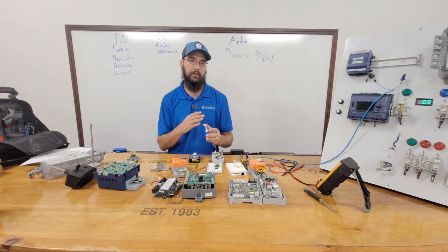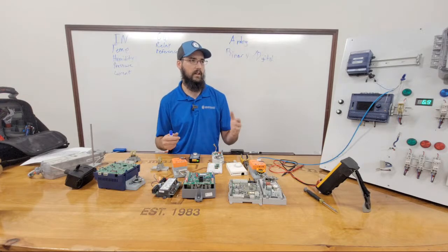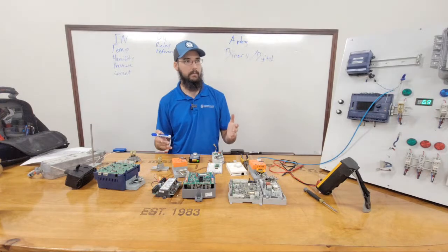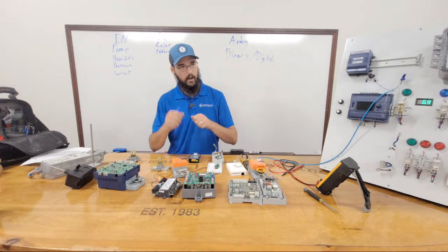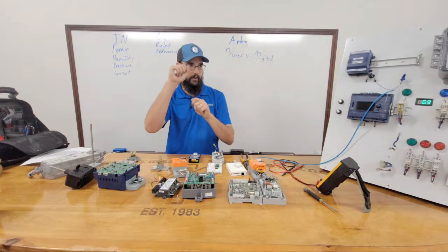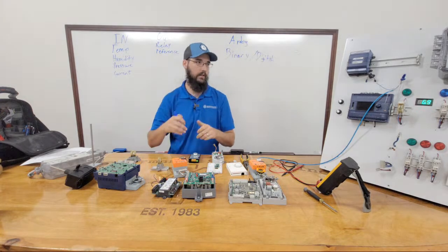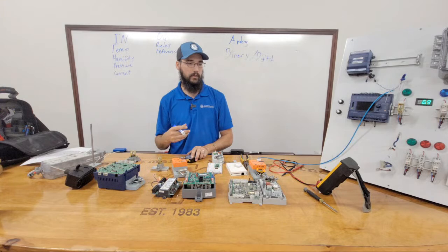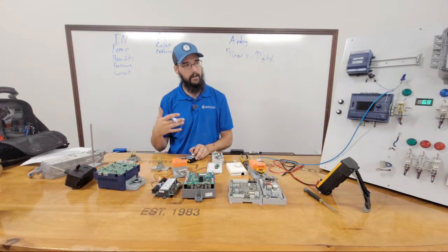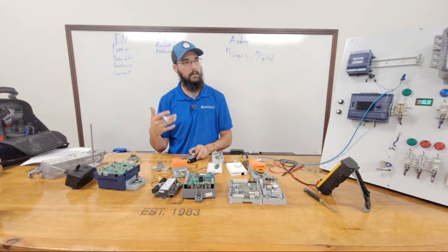Even though the milliamps are fluctuating, I think it'll be something like 20-something volts DC, typically. So if you walk up and you're testing and you see a weird 20-something VDC signal or voltage somewhere, then you likely are seeing a milliamp.